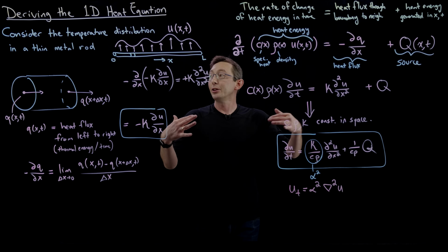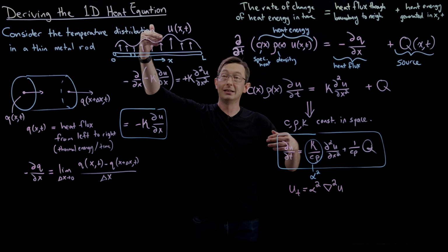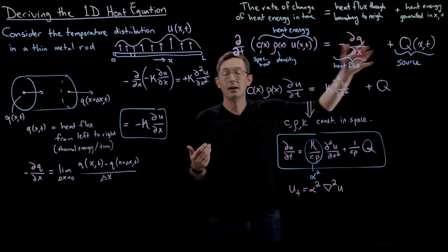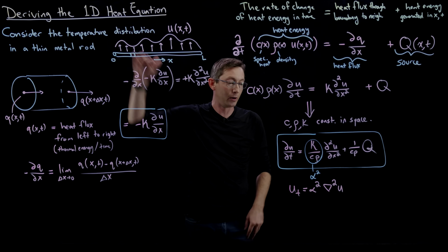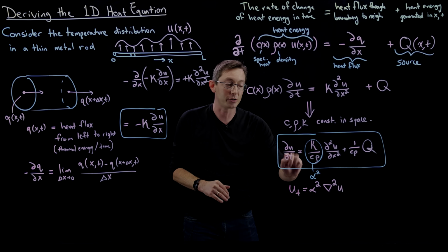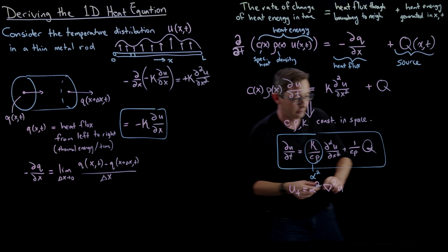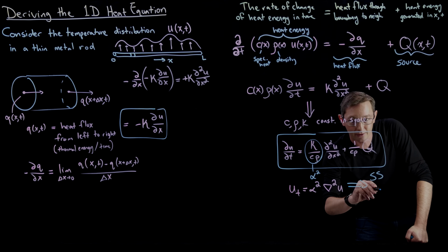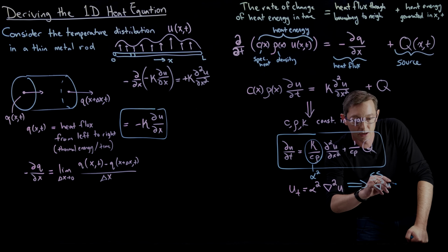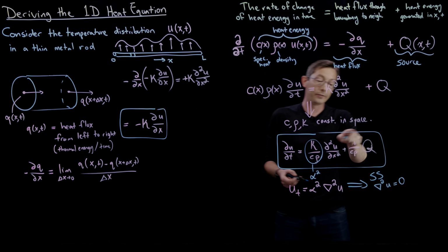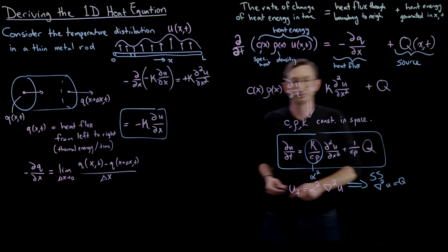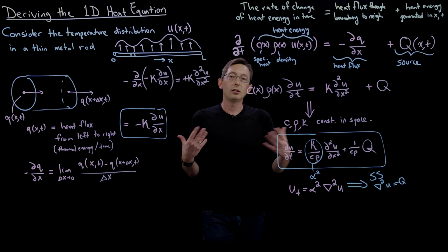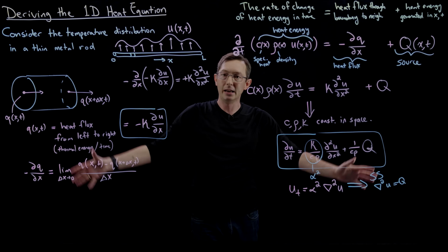So that's one thing we'll do. We will also look at how you actually solve for the heat distribution given initial conditions and boundary conditions and source terms. We will solve for the steady state heat equation. So if in steady state this partial u partial t is 0, and so in steady state we have the Laplacian of u equals 0, or if there's forcing, minus q. Okay, minus q, good. So that's all coming up to analyze these heat equations.